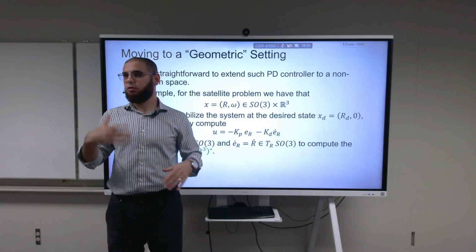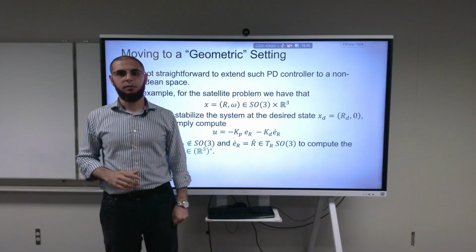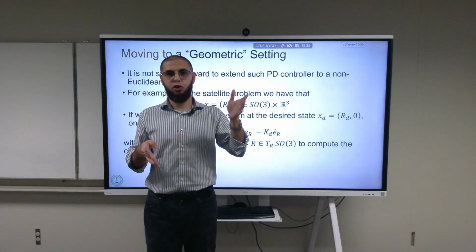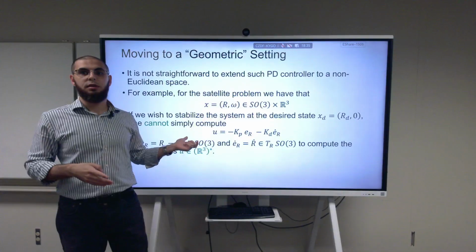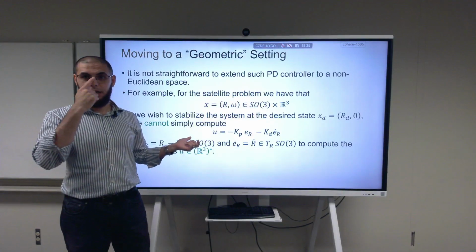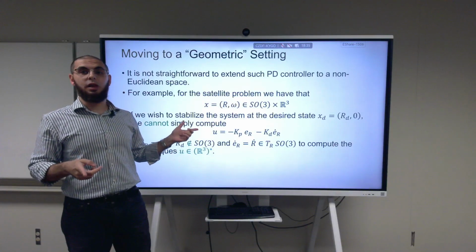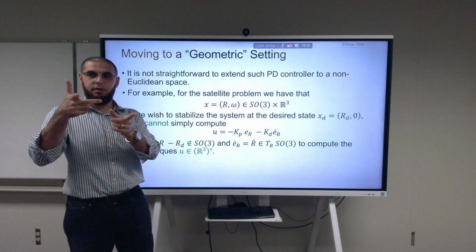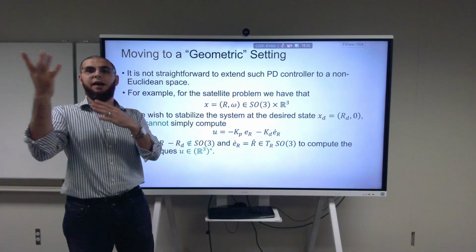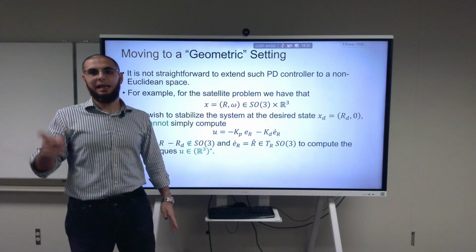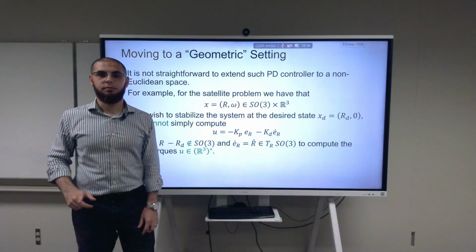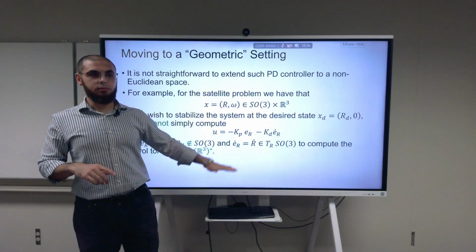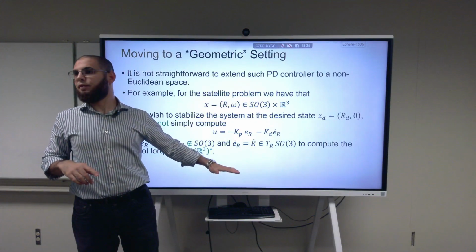In general, it's not. For a quadrotor, it will not be that simple. For a quadrotor, it's easy also because you actually don't have 6 inputs. You don't have a control wrench. No, but it is underactuated, no? It's underactuated, which means that I'm not actuating the force in the X and the Y in the body frame. So I'm only left with 4, and I have 4 propellers, so it's still invertible. That's exactly the assignment. That is why it does not move like this. Absolutely, yes. So linear algebra fails at that step.